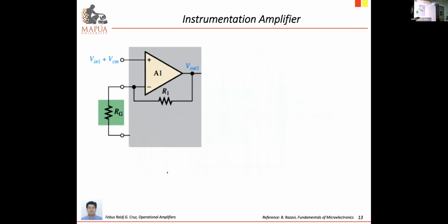Okay, clear? So we can now start analyzing amplifier 1. What are the signals in amplifier 1? We have V-in1. And what is the voltage here? V-in1 also. What is the voltage on this node? V-in1, and then on this node you have V-in2. Then you have Vout1. We are going to label the output of amplifier 1 as Vout1. Then current from V-in1 will enter the op-amp.